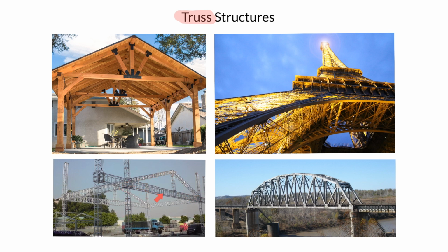You actually use truss systems because the benefit is that you need very little amount of material to span long distance. You see, this is a very long span, and that can only be achieved on lightweight with a truss system.